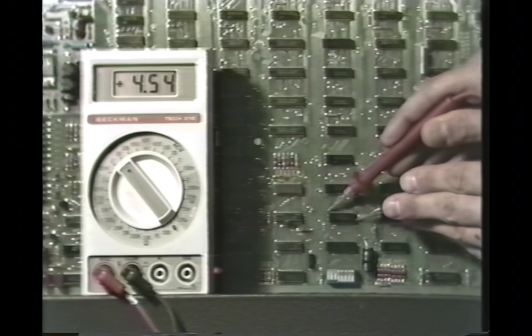a lower than normal reading at the output when you check the DC voltage. Well, standing alone, the DC measurement can point to either of two possible failures. Either the DC output of the regulator has indeed dropped due to a regulator failure, which would be the obvious first guess, or the low DC reading is being caused by excessive ripple in the power supply as a result of the defective filter capacitor. When you make the DC measurement, you have no way of knowing which of the two possible causes are creating the low reading that you see.